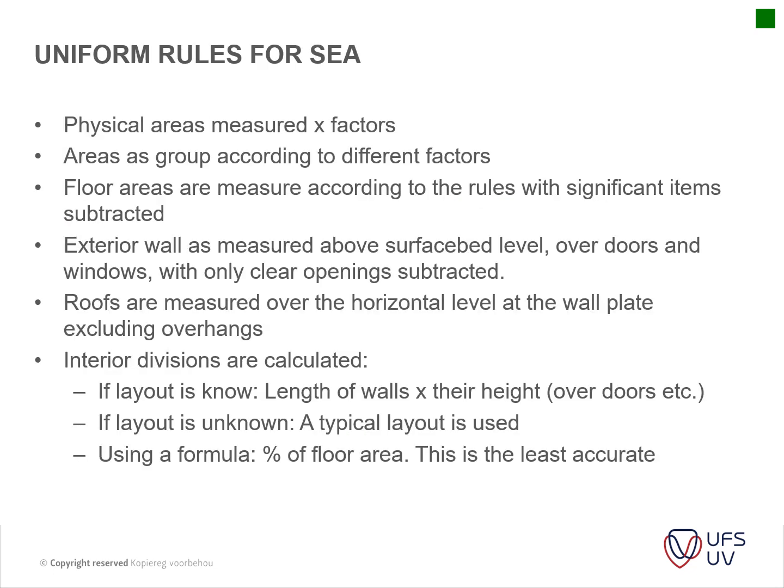Okay, the uniform rules for the storey enclosure area. So this is important, to know just the standard rules that apply to this method. Physical areas are measured and multiplied with your factors, as we've seen. Areas are grouped according to different factors. Floor areas are measured according to the rules, with significant items subtracted.